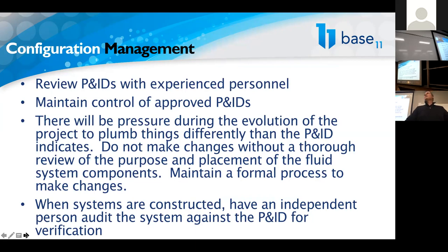The question is, should you minimize the number of fluid system components in your system, or over-engineer for every possible scenario? In my opinion, simpler is the absolute best way to go. All valves are going to fail. All valves are going to need maintenance. All valves cost money. So if you can come up with a reason to leave valves out of systems, I would absolutely endorse that.